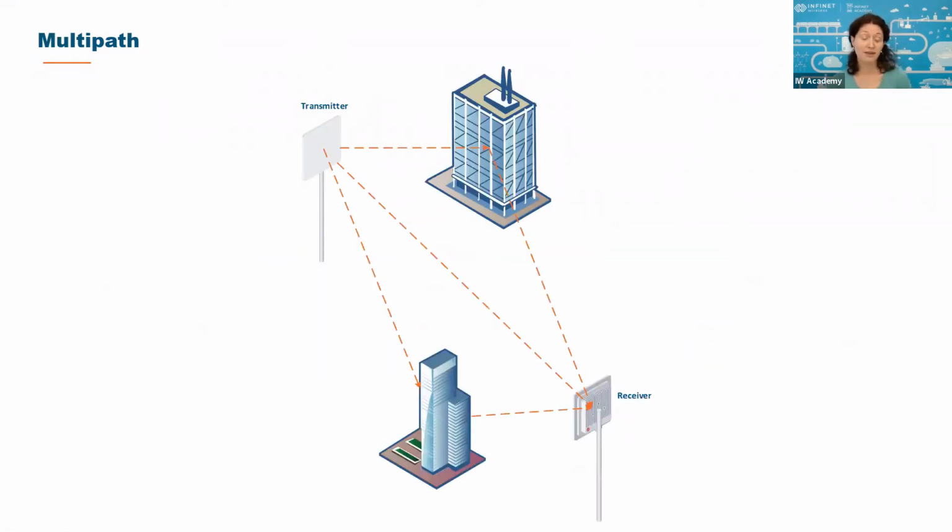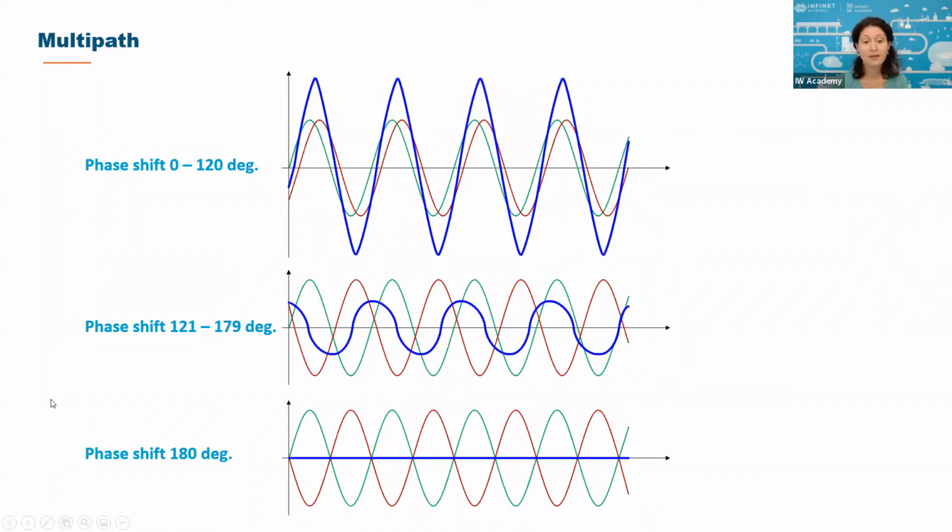In a multipath scenario, the reflection effect appears many times. So at the receiver side, many copies of the signal will arrive at the same time, but coming from different paths, as it is shown in the figure. This is the multipath effect represented in the picture. The reflected signal can differ from the original one by its parameters: amplitude, frequency, phase, and polarization.